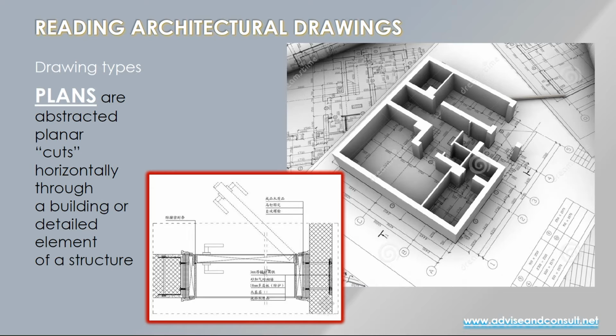Frequently comes up with issues like storefront designs, because you cannot open a door out into a public way. So that's why many of you may have seen storefronts that have a kind of a little recess where the door is, so that when you open the door, it's not swinging out into the sidewalk. So various kinds of plans, and we'll be looking at more of those in a short while here.